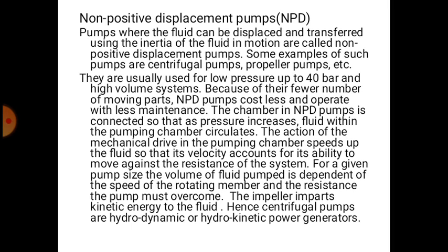Because of their fewer number of moving parts, non-positive displacement pumps cost less and operate with less maintenance. The action of the mechanical drive in the pumping chamber speeds up the fluid so that its velocity accounts for its ability to move against the resistance of the system.